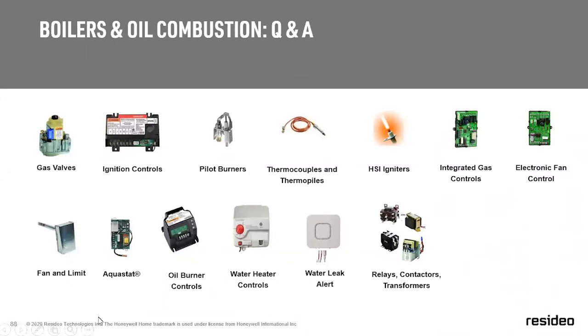It says, is the ignition carryover period adjustable? I'm taking that they're asking, can we adjust the time the igniter stays on? The answer would be the igniter stays on all through the trial for ignition. So if we have ignition immediately, right after that, the ignition will drop off if you have it set that way. But it does drop off, and it's not adjustable to say I want it to stay on 3 to 5 seconds after flame is proven.